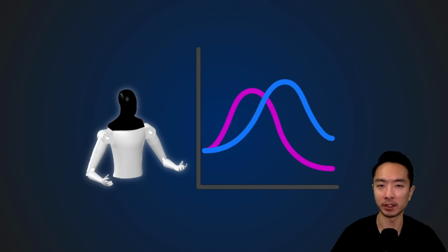So we just finished looking at how to simulate our TeslaBot using Gazebo and ROS to control. But what we're going to notice is that a lot of times when you're simulating things, you want to have a live plot of your data. You may want to visualize the joint trajectories or even the torque values as a function of time. Luckily, there is a tool called PlotJuggler. So I'm going to show you the steps and the commands you can use to set up your plots.